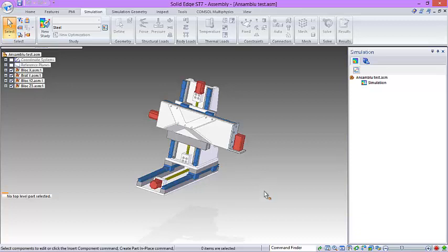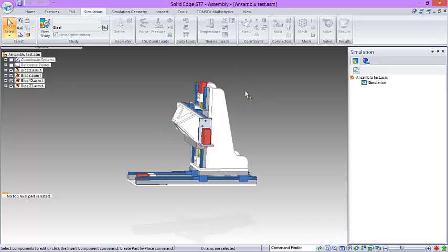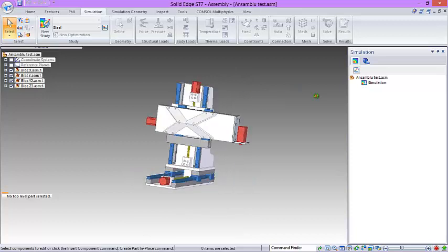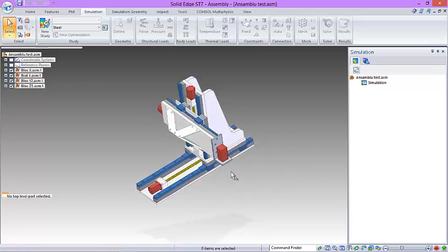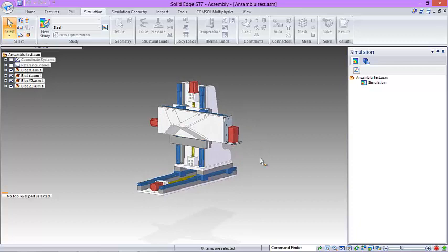because every time we have simulated, we went for the weakest point of the machine. So if you look here, the vertical block moving sideways is the weakest ratio of base to height. If it can take 55,000 in the y direction, it can easily take it in the x direction as well. Same thing applies to the fourth component. If it can take 20,000 newtons in the x direction, it can very well take them in the z direction as well.